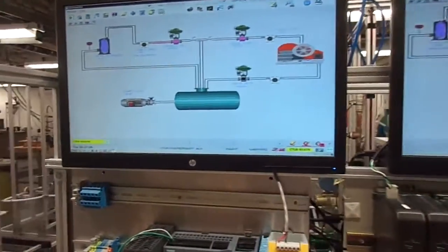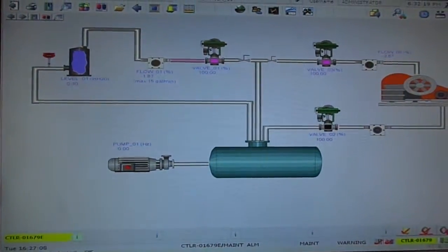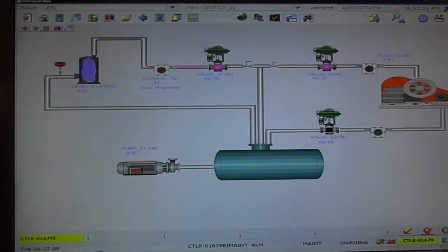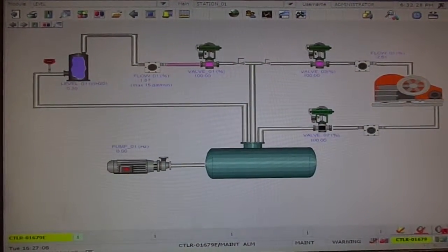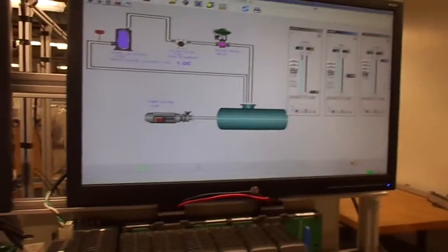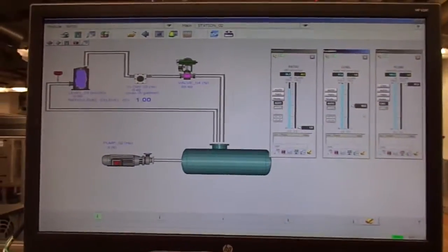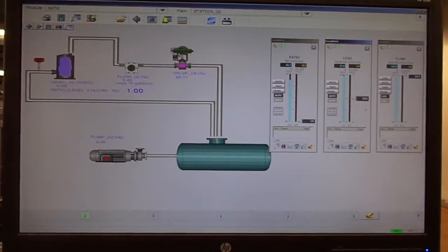Station 1 has the generator and the first tank, since they both are sharing the same flow, which splits. 60% goes to the generator and approximately 40%, which is varied every now and then, goes to tank 1. And the other monitor could monitor the other station and the other tank, which is supposed to maintain the ratio and the set point of the first tank.